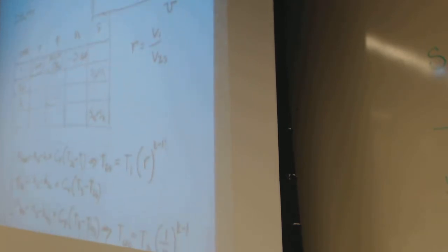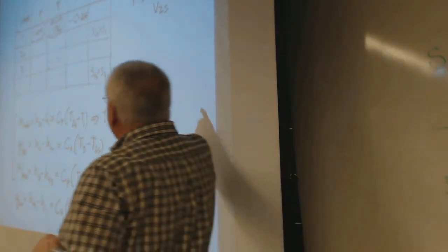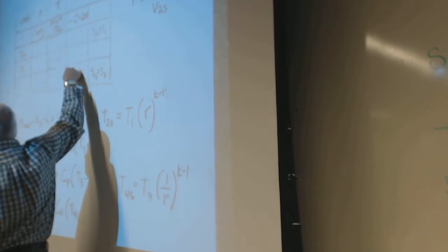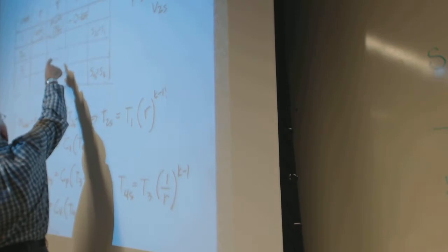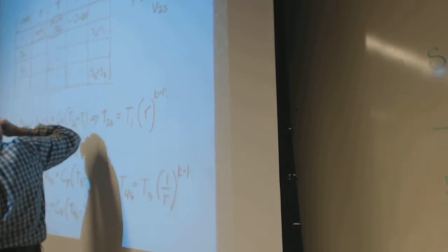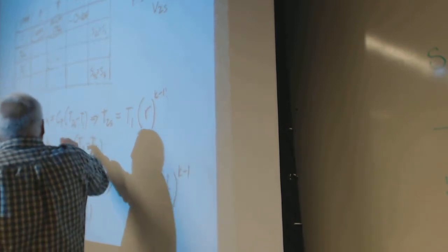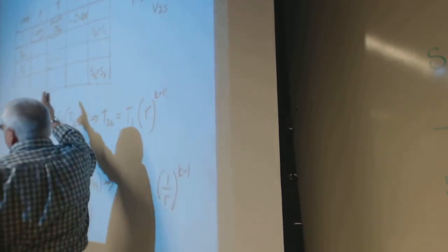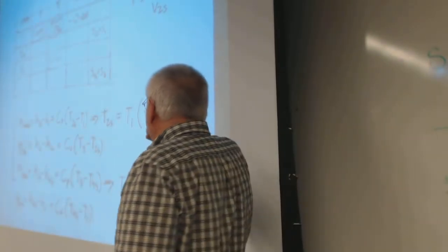the work, the pressure times volume. So, some of the formulas. In this case, if I can chase the temperature around the cycle, the difference in temperature is going to give me changes in H. This is all I really care about. So in this case, changing H is C sub P delta T. So for ideal gas cycles, chase the temperatures around, and you can use those to get your values.